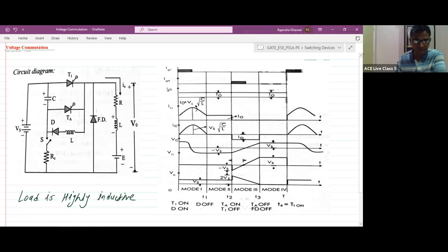Next, in order to turn off the thyristor, we have the supply voltage Vs, main thyristor T1, and here it is a load. Apart from these three elements, whatever other elements we have connected are all commutating elements. These are the external elements connected in order to turn off the SCR, whereas in natural commutation the external elements are not required. Now let us discuss the waveforms.